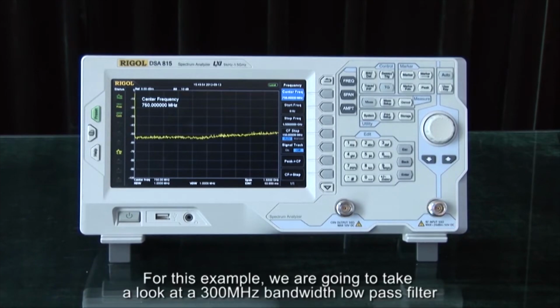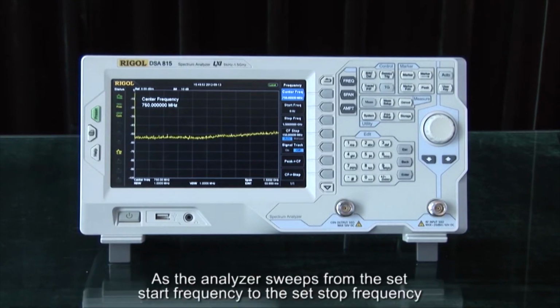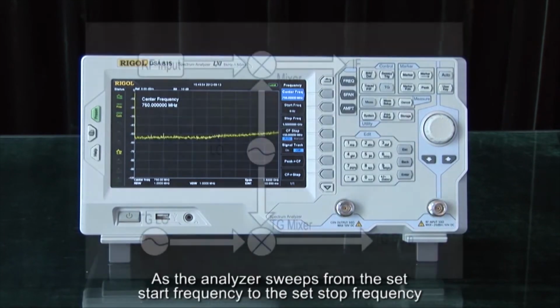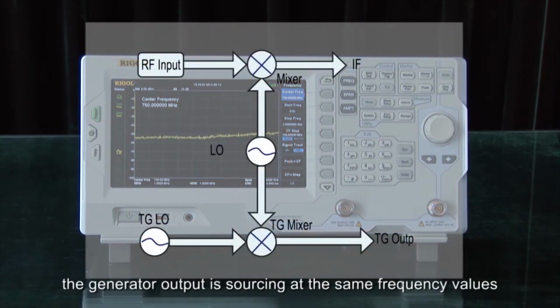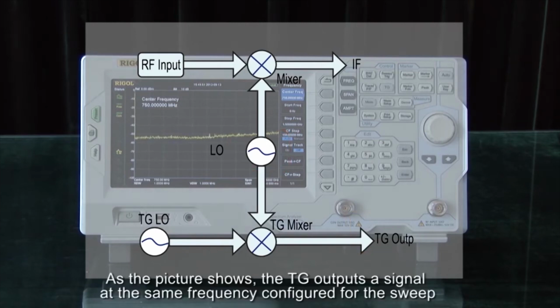For this example, we are going to take a look at a 300 MHz bandwidth low-pass filter. A tracking generator is a signal source which has its output frequency locked to the spectrum analyzer internal local frequency. As the analyzer sweeps from the set start frequency to the set stop frequency, the generator output is sourcing at the same frequency values. It tracks the input sweep. As the picture shows, the tracking generator outputs a signal at the same frequency configured for the sweep.